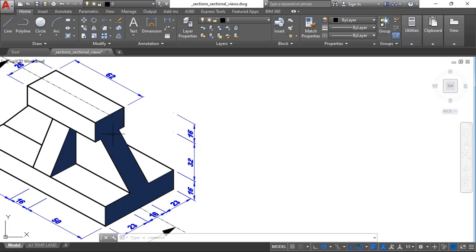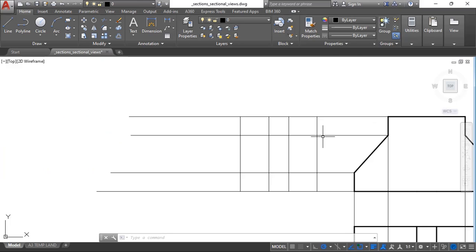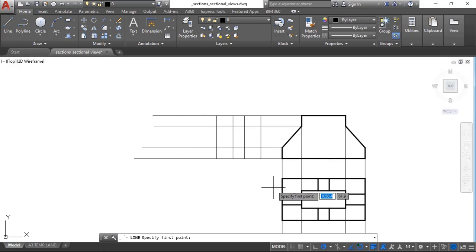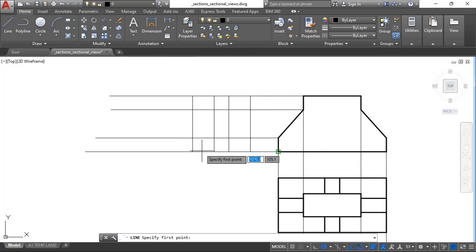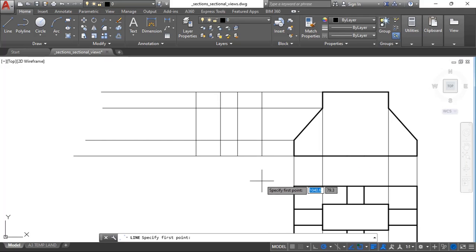Okay, so we are basically drawing a rectangle at the top, and it's 26 by 16, so it's in the middle. So same thing as before, I'm going to subtract. If you still remember those dimensions, we are supposed to move 18. Okay. Geometrically we are supposed to project the line from here to there, then you move it via an angle 45.